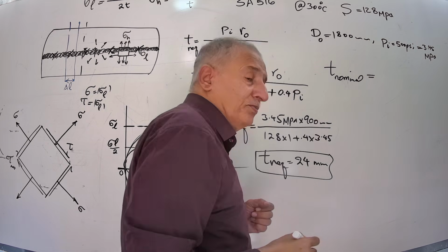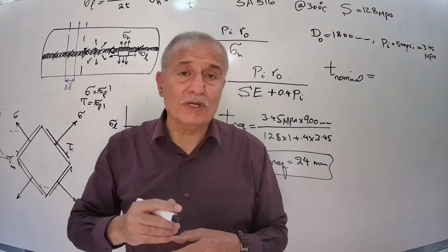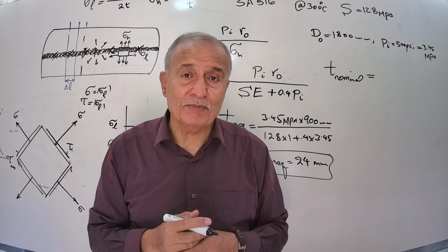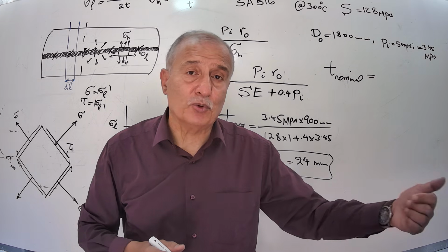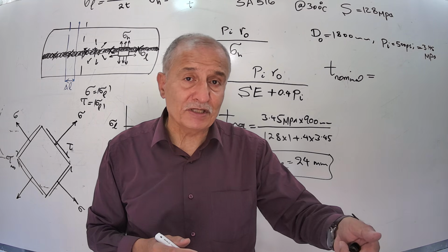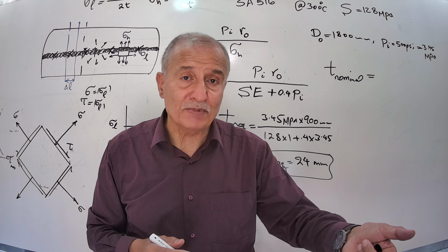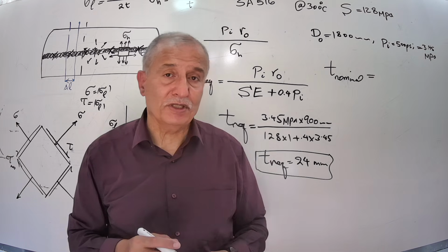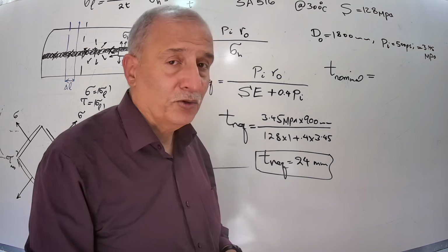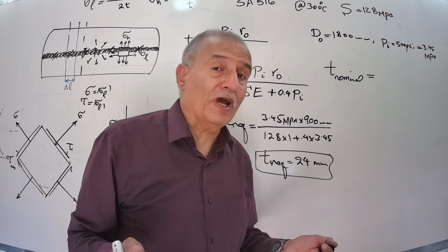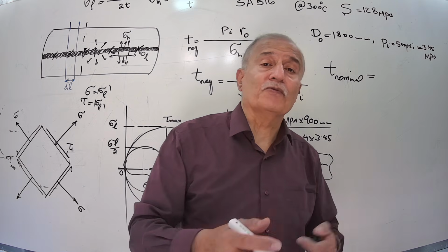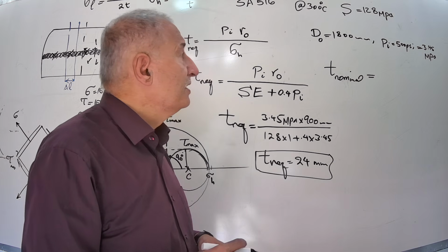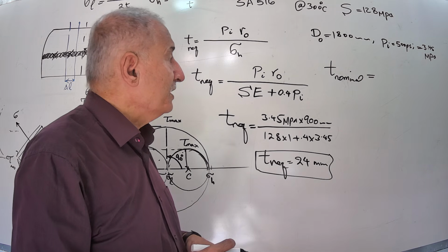And in ordering this plate, you must know each plate is produced by a mill machine. And there is a plus minus tolerance for the mill machine. For example, if you say that the nominal size of this plate is 20, when you choose it and measure it, it is 17.5 mm, not 20 mm. This tolerance belongs to the manufacturing machine, the mill machine. Each factory is different. Some factories say plus minus 1.1 mm, 5 mm, up to 40 millimeter thickness for the plate. Okay?